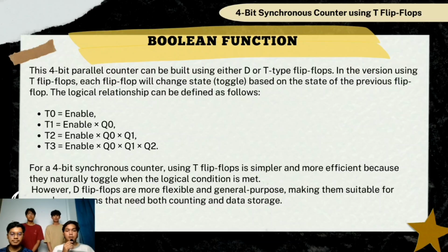A 4-bit synchronized counter using T flip-flop is simpler and more efficient because they naturally toggle when the logical condition is met. However, D flip-flops are more flexible and general purpose, making them suitable for complex systems that need both counting and data storage.